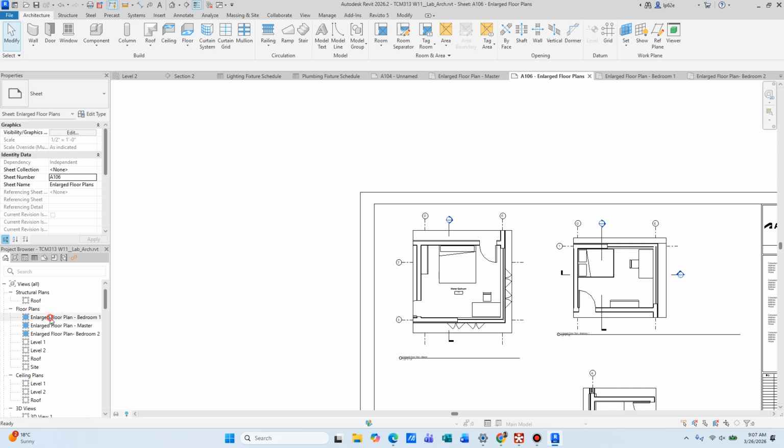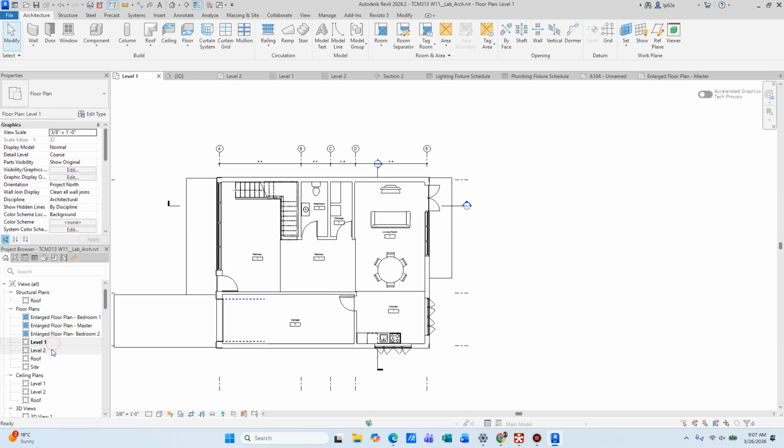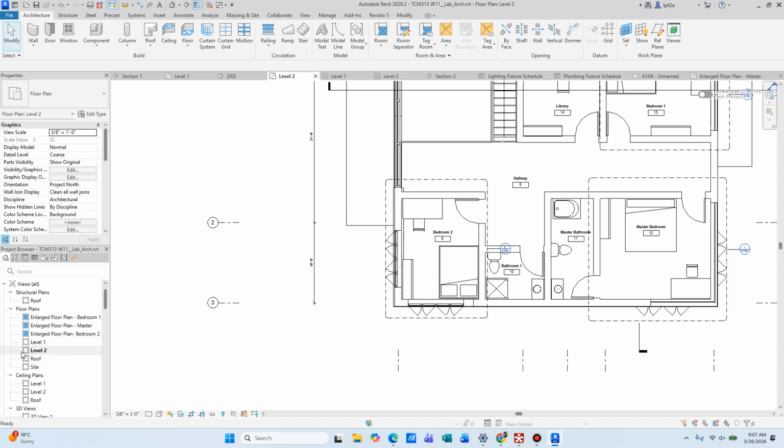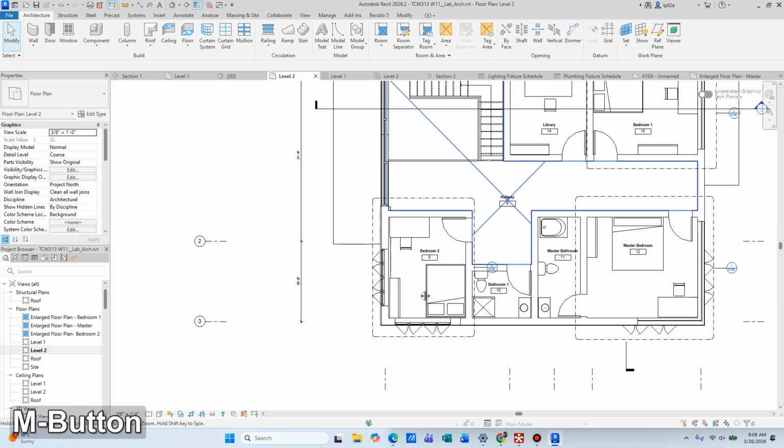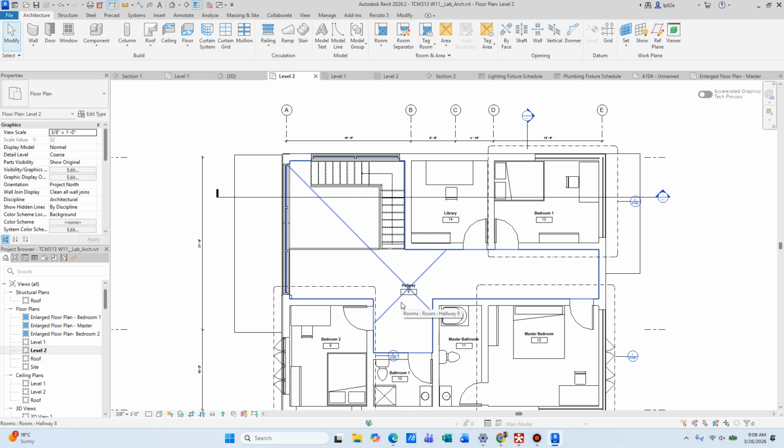You need to have several section lines that apply to callout views in this section view. We're going to get to that at 9:10. Meanwhile, you can feel free to adjust your enlarged floor plans, placing callout views, or setting up your sheets.